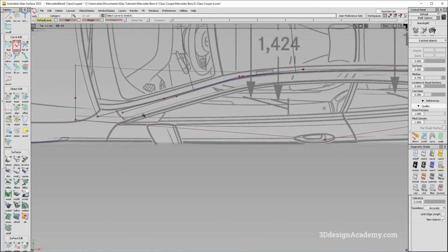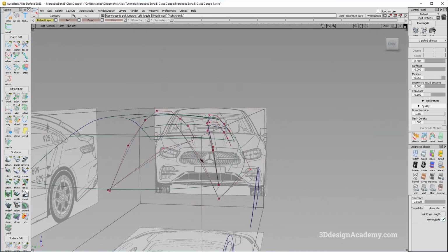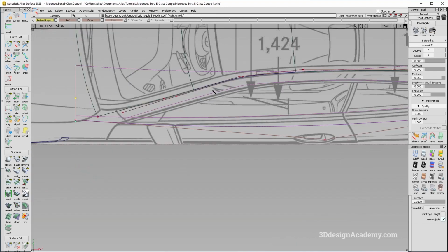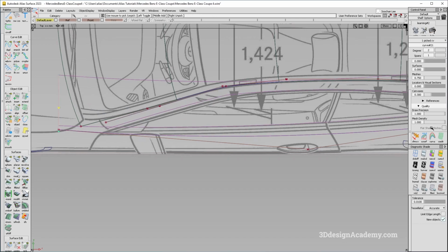And I'm going to pull this out. So let's see. One of the things that I'm going to do is reduce the amount of crown that we have on the curve over here. Because the more crown that we have on the glass, usually that twists the A-pillar a little bit more. So as long as the gesture is similar, I would prefer to minimize the amount of crown on this one. So let's see if I can just pull that a little bit more in. And actually, well, I'm not sure. Maybe I should just pull it back out because we are getting farther away from target.